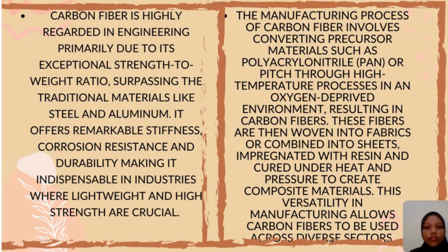Second, the manufacturing process of carbon fiber involves converting precursor materials such as polyacrylonitrile, PAN, or pitch through high temperature processes in an oxygen-deprived environment, resulting in carbon fibers. These fibers are then woven into fabrics or combined into sheets, impregnated with resin and cured under heat and pressure to create composite materials. This versatility in manufacturing allows carbon fiber to be used across diverse sectors.